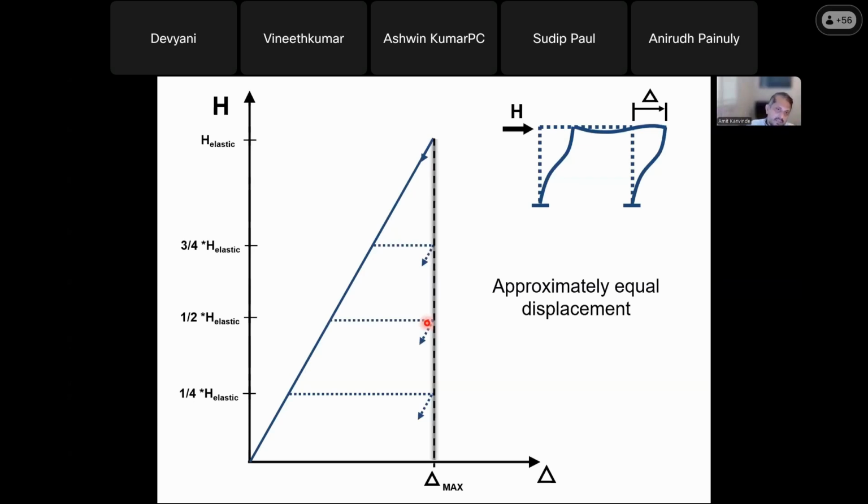Remember, if you do this in any other context, if you design a bridge this way, if you design any other kind of structural system this way, which is quote unquote load control, you actually have the weight of a truck on a bridge. And if you design the bridge for half the weight of the truck, the bridge will collapse regardless of ductility because you have the full weight of the truck on the bridge. However, when you're thinking about earthquake shaking, it's not exactly that.